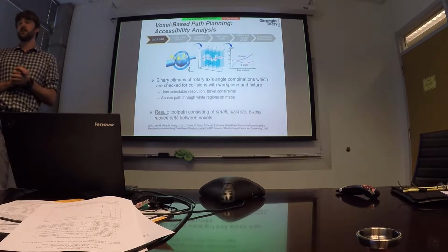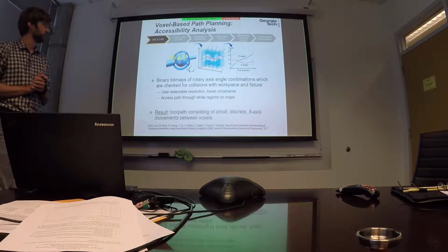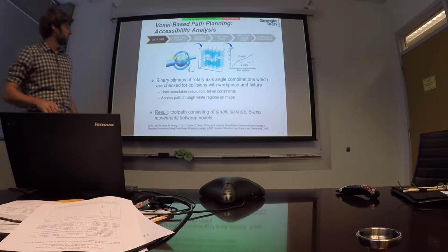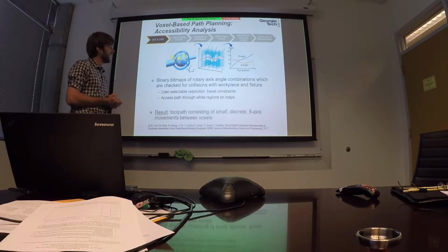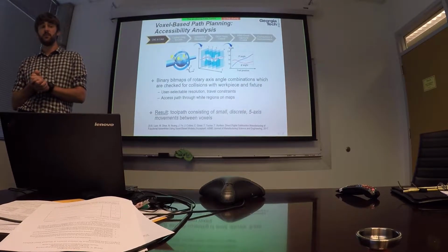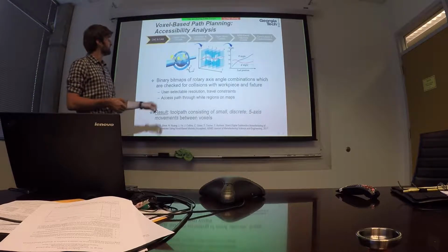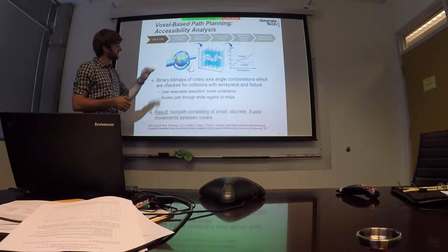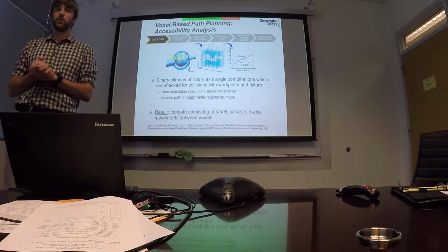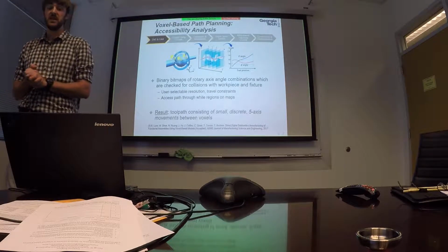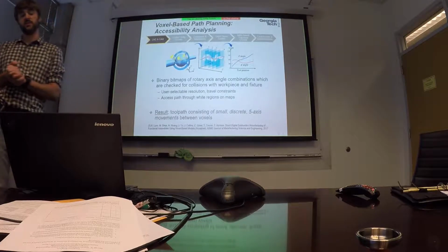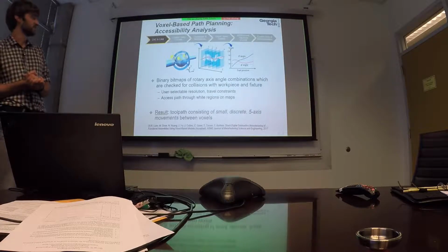The next thing we need to determine is the rotational axis position, and we'll do this with what's called the accessibility map algorithm. So again, here we have the ball joint, and if we want to determine what rotary axis angles are suitable and will not result in a collision, we can position the tool at every point along our tool path and check each combination of the rotary axis angles theta and phi to see if they will cause a collision with the workpiece or the fixture or the machine structure itself.